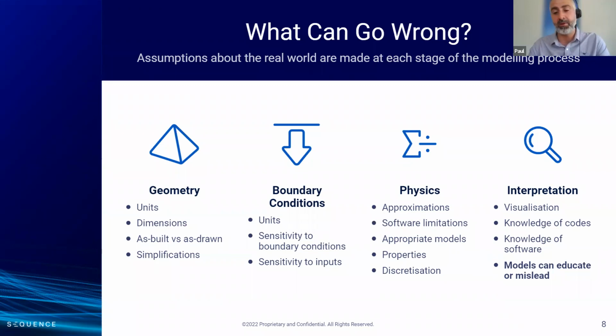And one of the big areas, common mistakes I see, especially in fluid dynamics, is insufficient mesh refinement in the boundary layer and areas of interest. And that can have a huge impact on the results that you have. It's just really easy to get caught out. Sometimes it makes little difference, and other times it makes a huge difference depending on what's happening in the flow or in the problem that you're trying to solve. So it's always important to be aware of that.